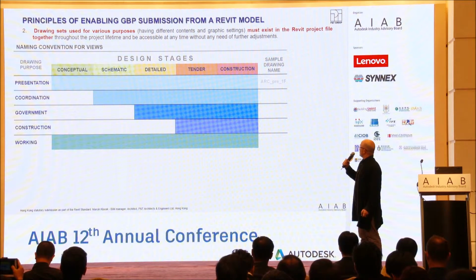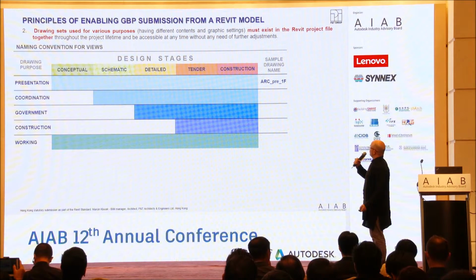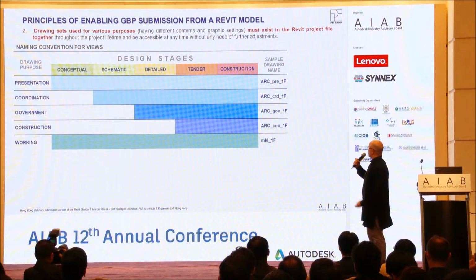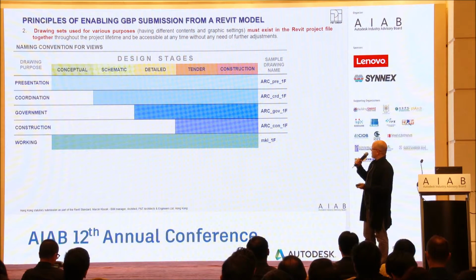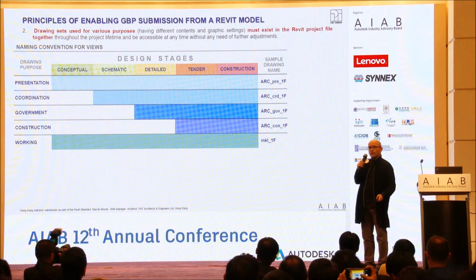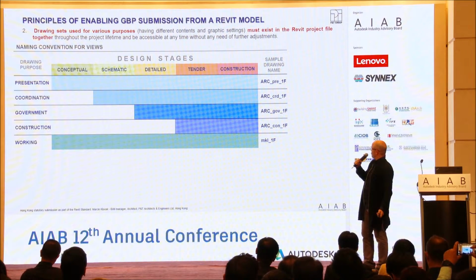Corresponding to this are names. So we call the presentation type of plan with the PRE part in the name. Then CRD for coordination, government, construction, and this third one, which is actually a personal working plan, or an example of a personal working plan, which is intentionally written with small letters so that you can differentiate it very easily in the project browser in Revit.